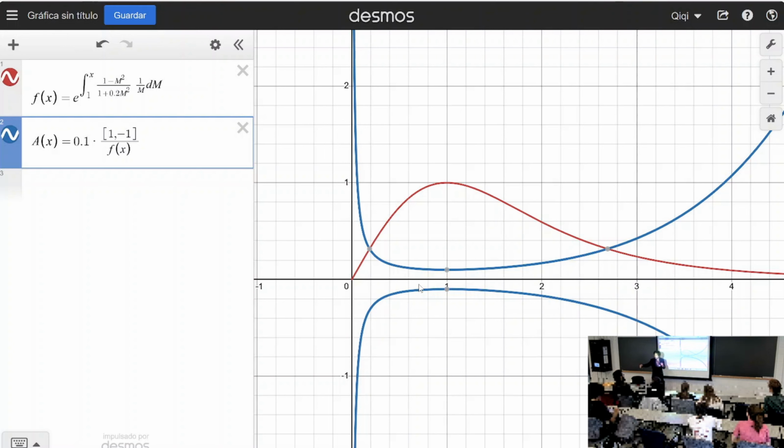But that calculation assumes everything is isentropic, which means no shockwaves. By that calculation, if you calculate a mass flow per area that is this, that means it's impossible. Okay? That means two things. One is that the nozzle is not going to operate solely in this region. And two is the flow is not isentropic somewhere. Yes? So we would use the jump conditions, because then there will be shockwaves. That's what I want to talk about for the remainder of the lecture.